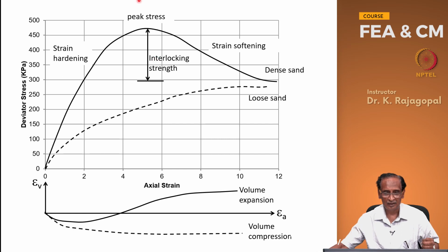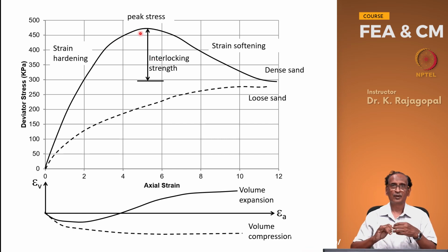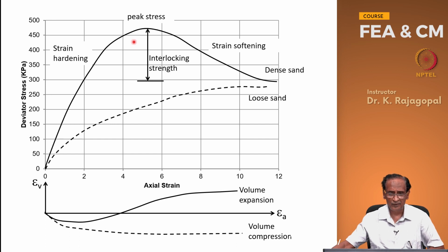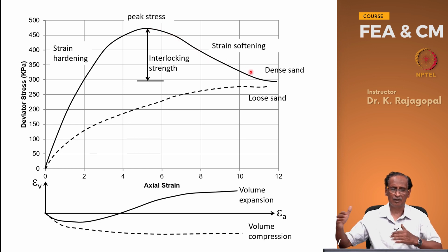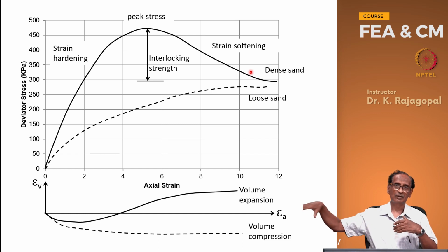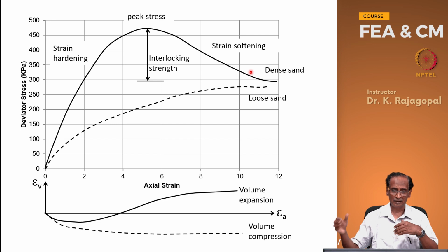and this is what we see right from our undergraduate days on the soil behavior. We know that a dense sand or an over consolidated clay, when it is subjected to shear strain, it will have a nice peak, and then beyond that it will undergo some strain softening, and then at a very large strain the stress will remain constant, and that we call as the critical state.